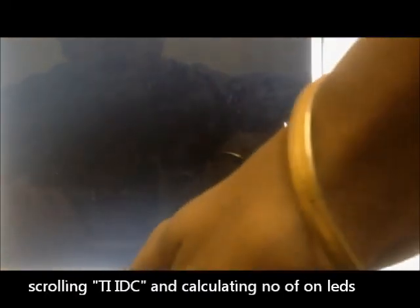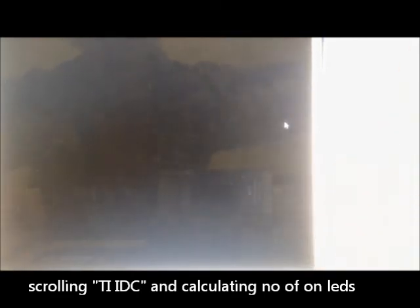Let's say I want to scroll TI Innovation Design Contest for my scrolling. This counter here shows the number of on LEDs at any given moment of time. It increases to a steady value and then decreases. The peak value of this counter shows us the number of on LEDs, and from this we can calculate the maximum amount of current that would be drawn at any given moment of time.